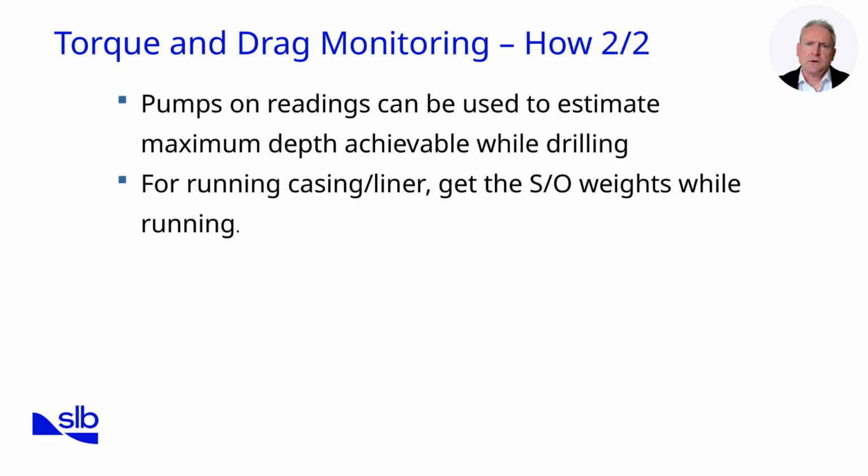Continuing the discussion on how torque and drag data should be acquired and applied. Beyond basic pickup and slack-off procedures, we also use circulating measurements to estimate the maximum achievable depth while drilling. By comparing drag trends during circulation, engineers can determine if the wellbore condition will support further progression without intervention.